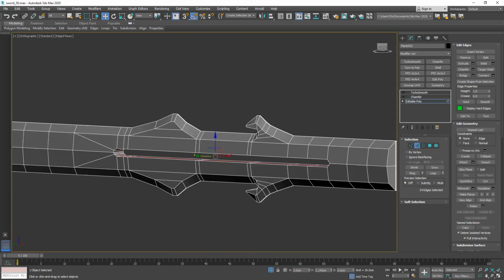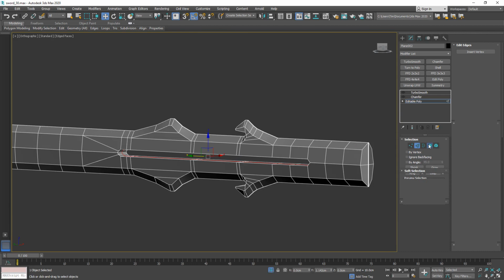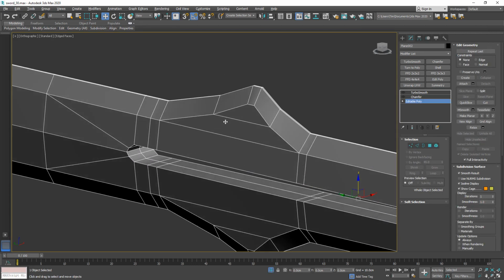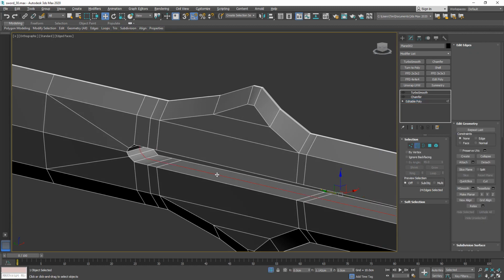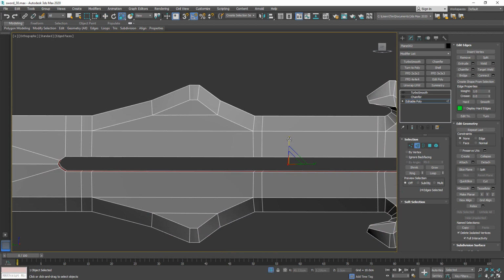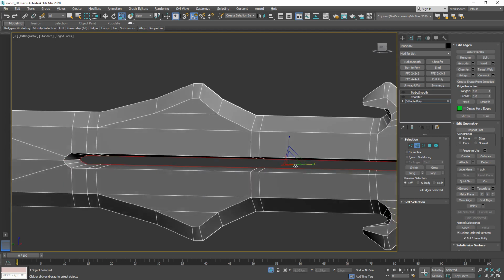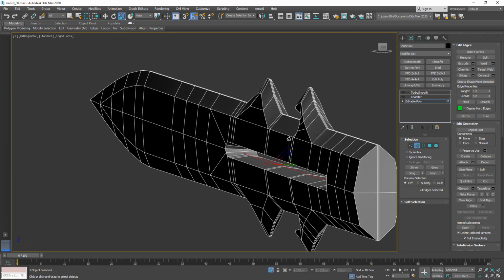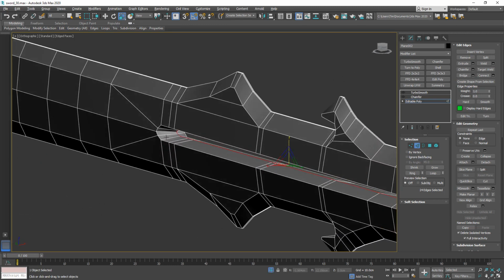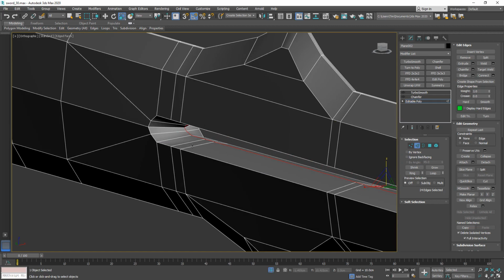So now there's one thing to do. Let's go back here to our edge mode and make an edge loop here in the center, convert it to polygons and auto smooth it. And actually there's one more thing that I want to do. Let's go back here to that selection that we just had. And I want to go over here to our scale mode and bring that down a bit here on the Z axis and also on the Y axis. Not too much, but just enough so that we actually see that there is some depth in there and it's not just this perfectly cut off shape.